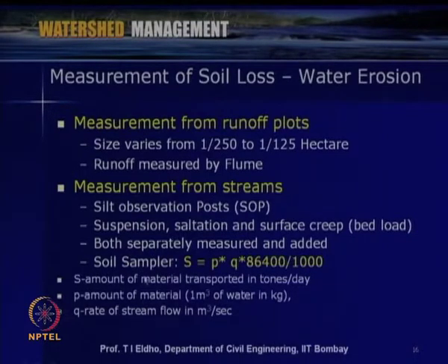For example, if you are doing sampling, we can take samples and identify how much erosion takes place. We can use this equation: S is equal to P into Q into 86,400 divided by 1000, where S is the amount of material transported in tons per day, P is the amount of material, and Q is the rate of stream flow in meter cube per second.